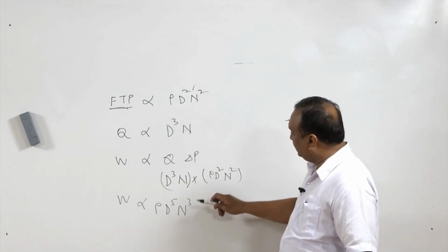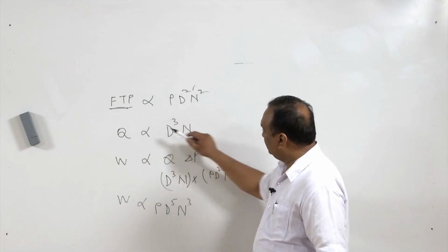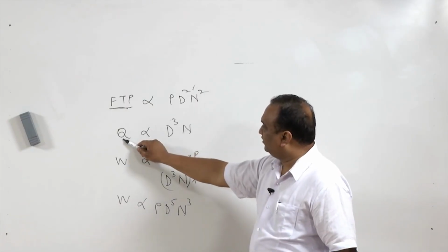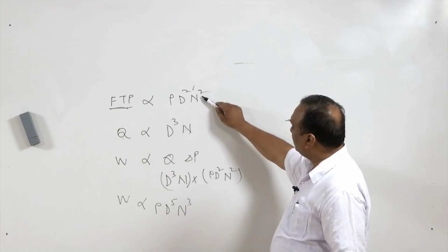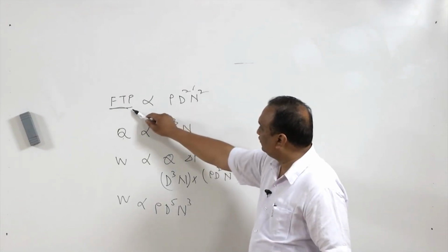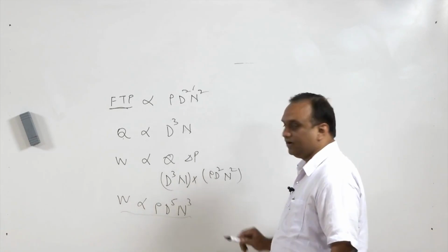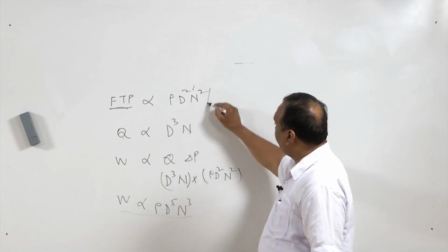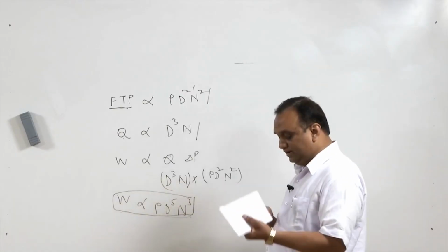So, you can imagine when we increase the RPM of the fan by some percentage, the variation in flow rate will be linear, the pressure will vary as the square of RPM, and the power consumption will vary as the cube of RPM. This information is required because often there is variation in fan RPM due to a variety of reasons.